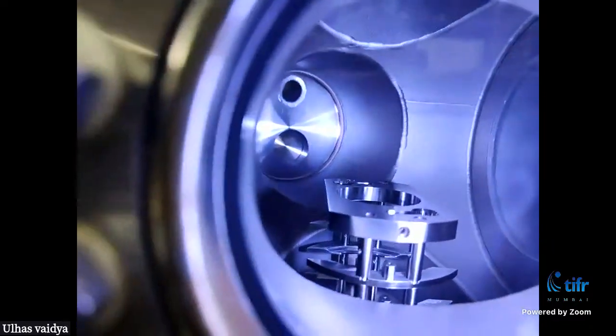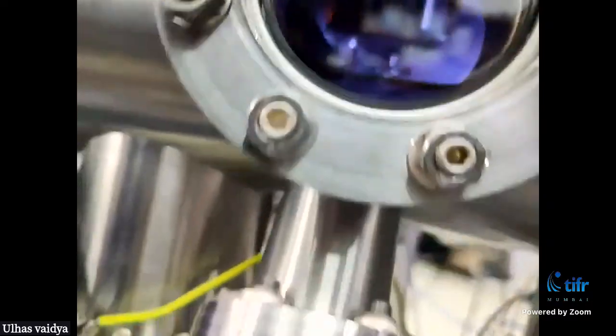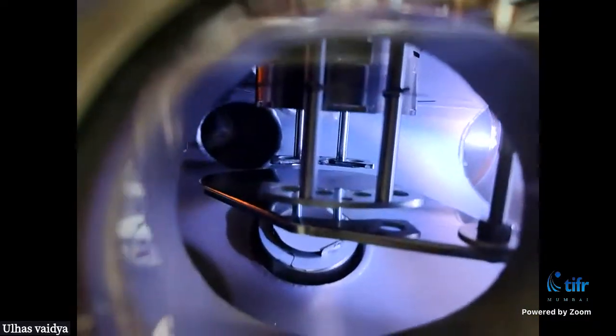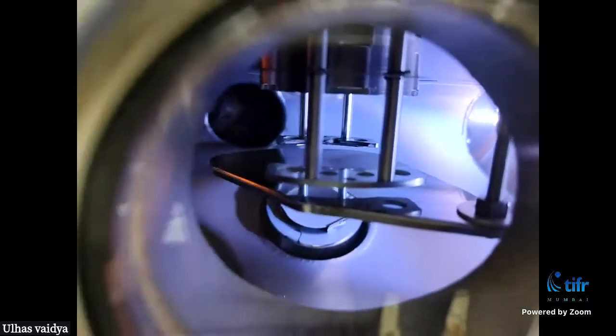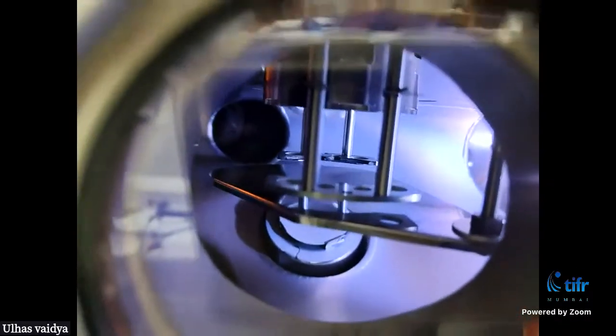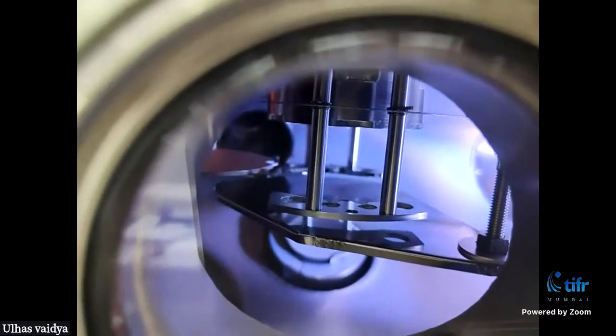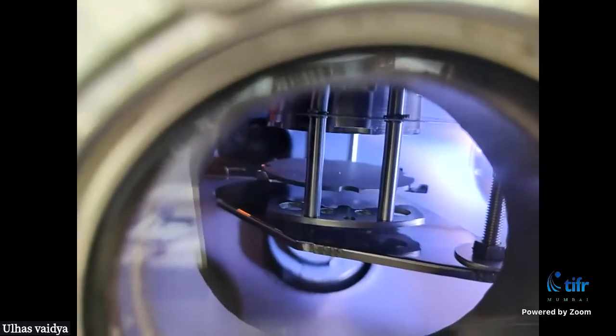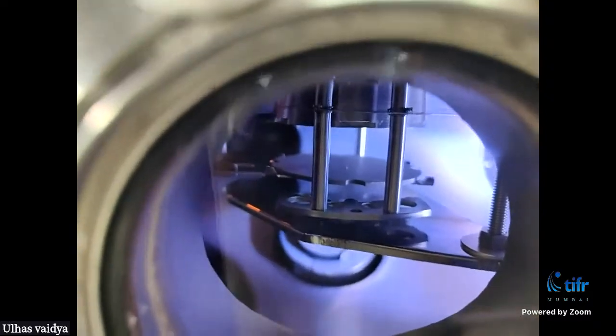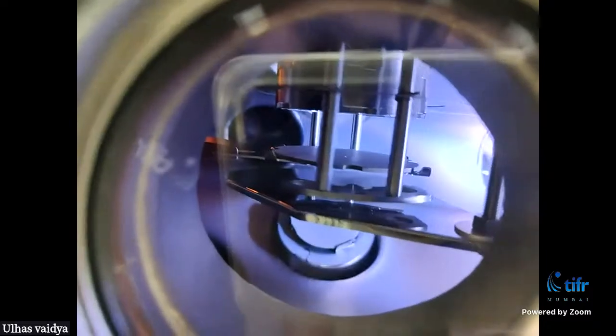All the way. You can see. The substrate is in the horizontal arm, in the back. You cannot see it right now, so maybe you can also look into the camera. Now I will move the horizontal arm just above the manipulator. Now I have to see if it is aligned. The substrate has entered the manipulator stage.